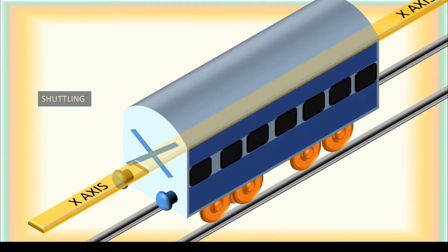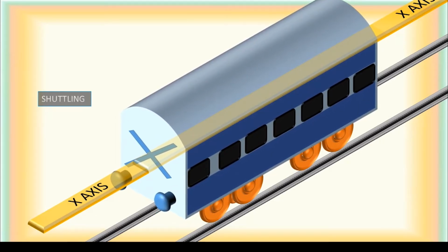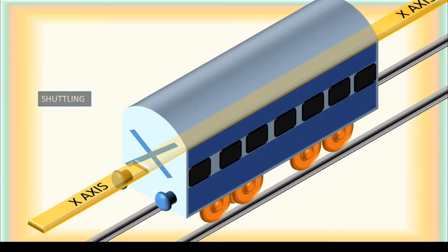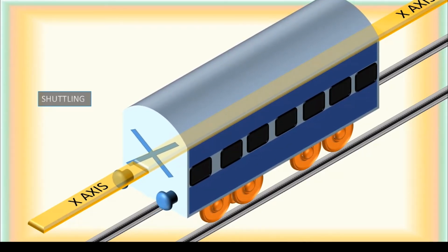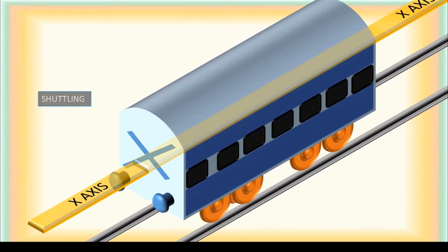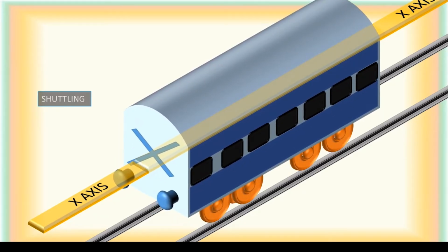Track will not contribute in this except in gradients. अगर आपका track gradient में है, then we will contribute into it. Otherwise, we are not going to contribute. I mean to say that track defects are not going to contribute. Track design parameter, if our track is in gradient, then certainly we will contribute in it. Otherwise, operating features and some rolling stock defects like coupler defect can mainly affect this movement. So this movement is known as settling movement.